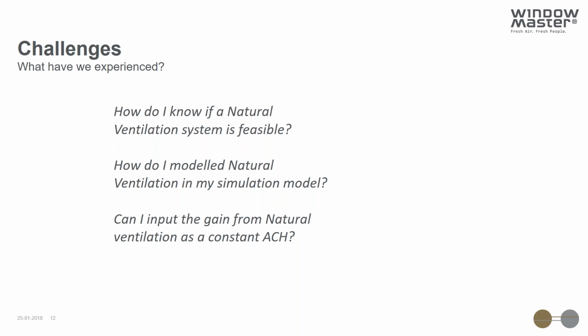And then in general, how do I model natural ventilation in a simulation model, and in connection to this, can I just input the natural ventilation as a constant hourly air change rate? These are normally the restrictions we have, that people will turn away from natural ventilation because just the simulation process can get too complicated, and the risk will be increased of mistakes.